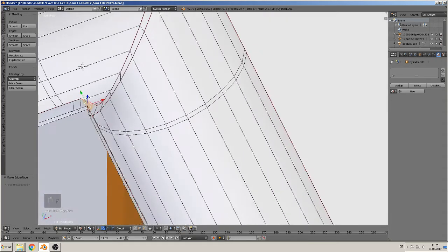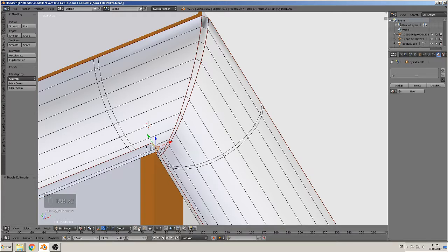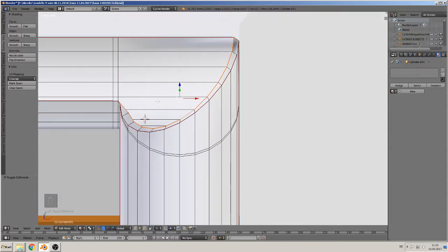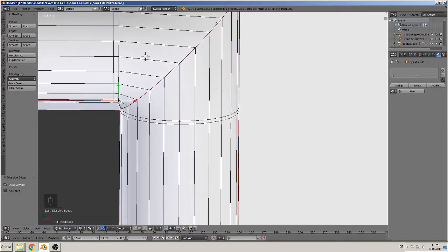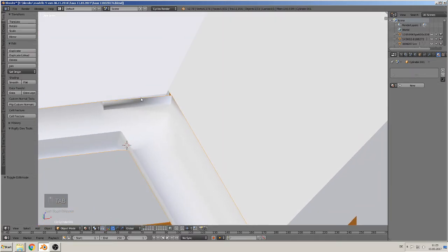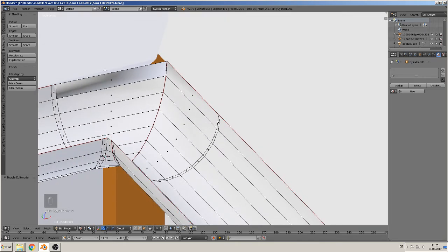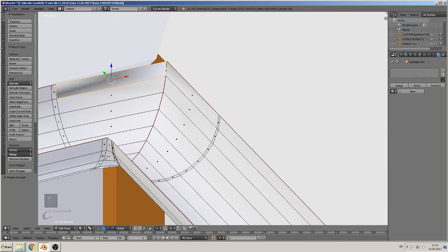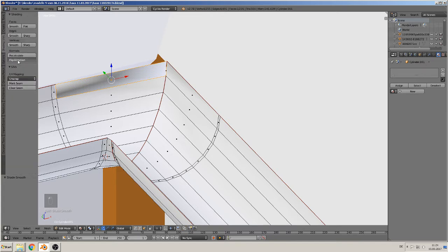So we have closed that. Now we need only one of them, so we can mark that line and dissolve them. X, dissolve edge. And then we have only one line, and that is real straight. Here we have a normal arrow that you can make with flatten, or you can make it with smooth, but then you must flip the direction.